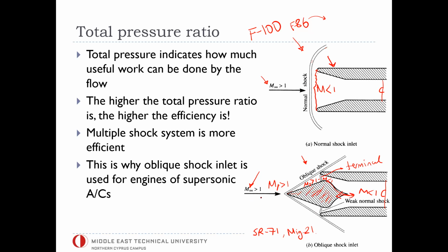The purpose of this is that depending on your flight Mach number, it can move back or forward so that it will always keep the shock wave attached to this point here and to this point here. If the shock wave is not attached to these two points, for example if it's like that, it's also an inefficient design and inefficient condition. Or if it's too shallow, it goes inside the intake, which is also an inefficient condition. So in nominal design operating condition, you would want this oblique shock wave attached to here and to the lip of the intake.